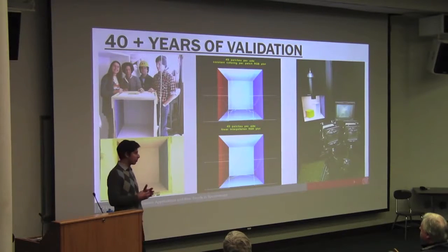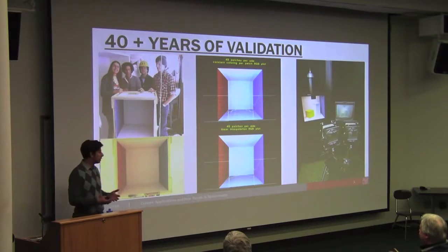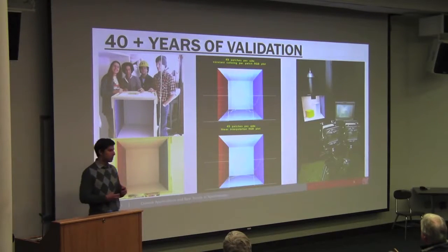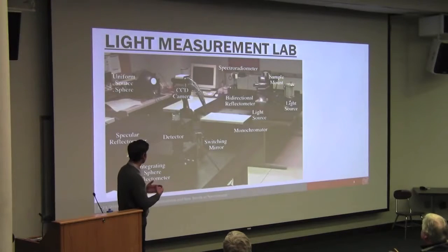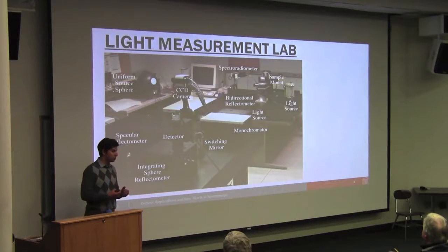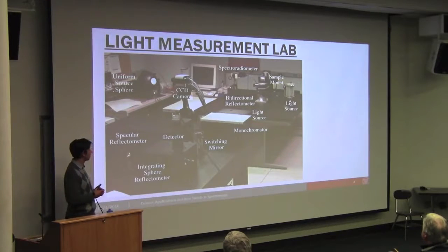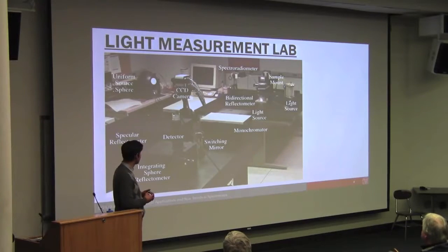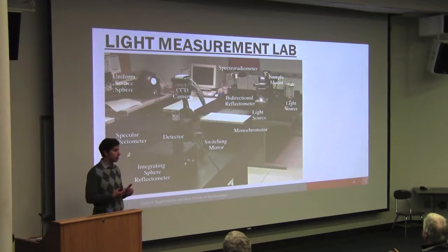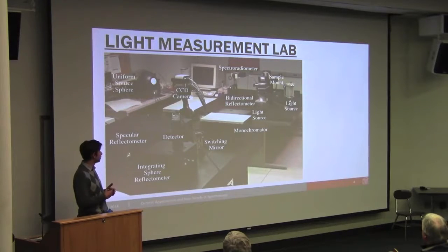Granted, it's only a box, but for 1970, this was a big deal to actually validate something. Nowadays, obviously, we want to validate large vegetation and a lot of different models for buildings. So Don initially set up to do his bidirectional reflectance function validation, with a reflectometer that did things in the visible range, measuring basically between 360 to 720 nanometers, set up with 3 degrees of freedom.